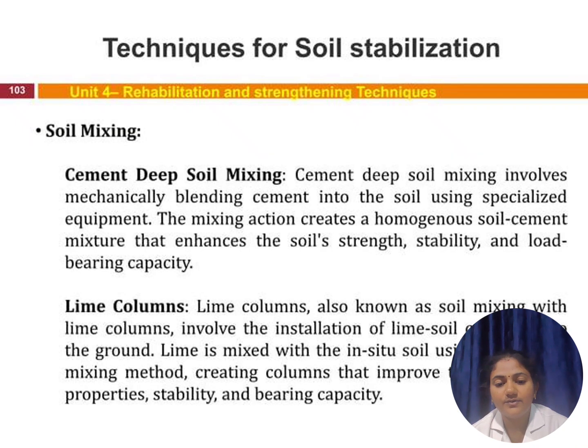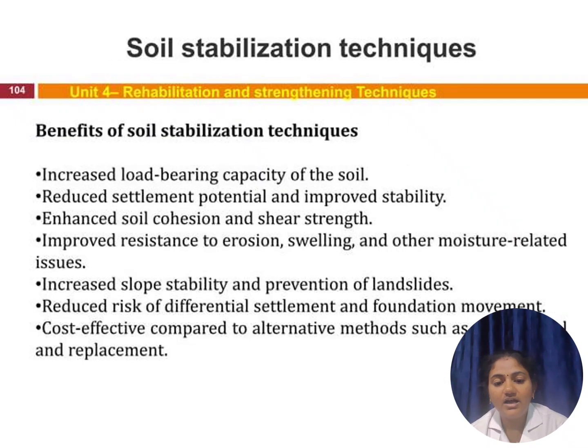Then soil mixing is done by cement deep soil mixing and lime columns. The benefits of soil stabilization are increased load bearing capacity of the soil, reduced settlement potential, improved stability, increased slope stability and prevention of landslides, and it is cost effective compared to alternative methods of replacement.